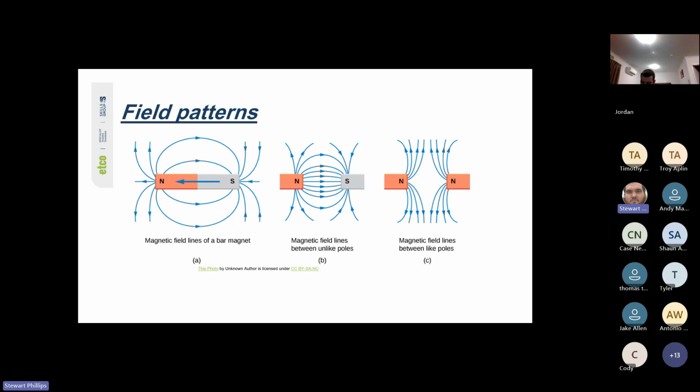If the generator is not moving, then the magnet's just sitting there. It's not creating an alternating field. If there's no movement in the field, there's nothing for the electrons to chase. And if the electrons don't have anything to chase, they're not going to move. So that's how the EMF is generated, through the changing of the magnetic field. If there's no changing magnetic field, we don't get an EMF. Does that make sense, Sean?